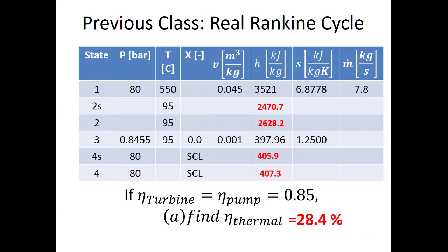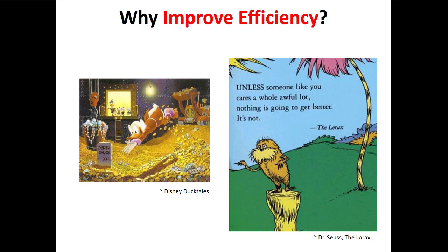We did an example problem before about this 4-component Rankine cycle, and we saw that we got an efficiency of just under 30%. Now we know that we can't compare the performance here to 100% efficiency because that's just impossible. So the impossible performance that we want to compare to is the Carnot efficiency, which even though it's not possible, at least we could asymptotically approach. And I think in this case, the Carnot efficiency was in the mid-50s. So we have some room to improve here.